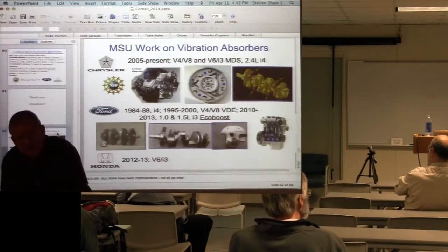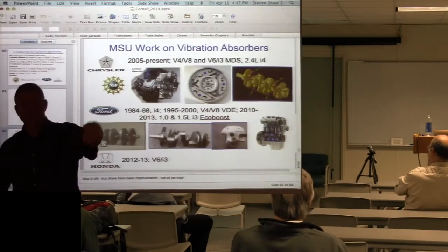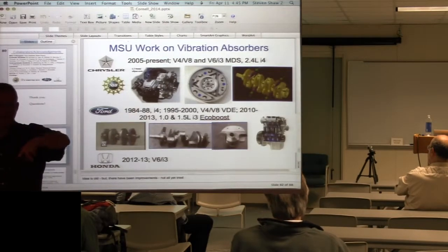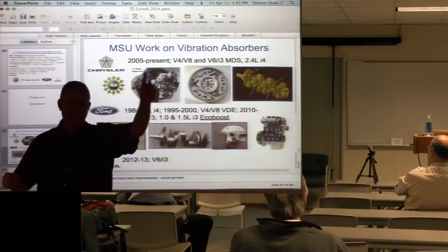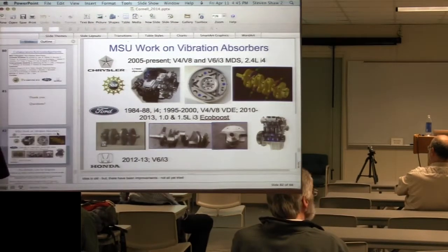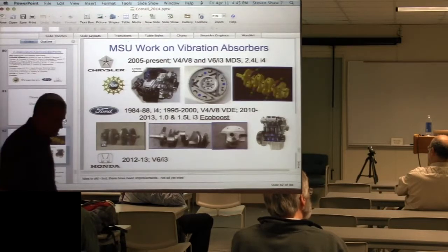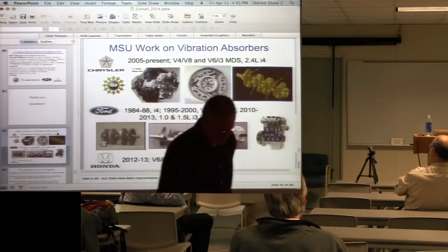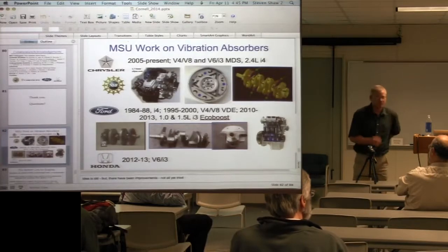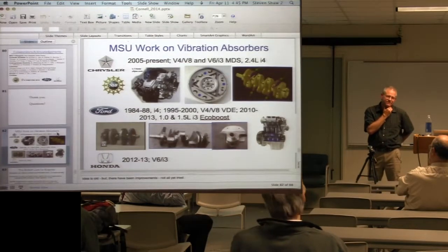Yeah, the other thing is that the absorbers aren't the only thing that are distributed. The torques are also distributed, right? And so you're getting these pulses once every 2 crank revolutions at different places. And that's what we have to put in the model also. So that'll affect, I'm thinking of transmission line models. Yeah. Where you have LC, LC, LC, LC. And when you look at the spectra, you get stop bands and pass bands. Right. And maybe that's something to do with the locking that you get there.